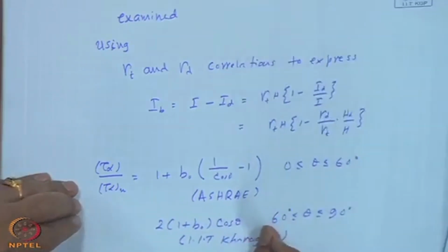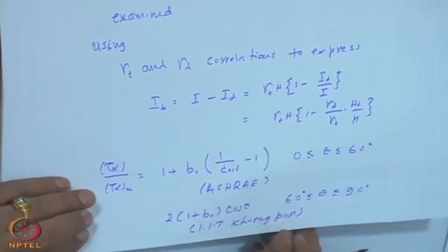So, in a nutshell, we have got the preliminary preparations, that is how do you process the solar radiation falling on in general a tilted surface and a solar collector in particular, and then how do you calculate the associated transmittance absorptance product for a flat plate collector having 1 or 2 glass covers.